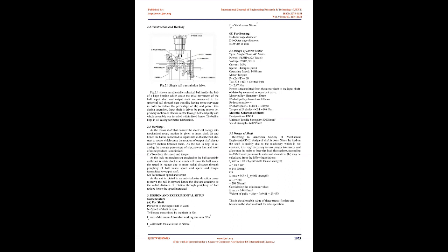2. Principle of operation. 2.1 Single ball transmission drive. Single ball transmission drive works on the principle of continuously variable transmission, CVT. In such transmission, a device or mechanism is designed in such a way that speed reduction or acceleration of speed is achieved continuously with respect to time, operation, or process. Fig. 2.1 shows an adjustable spherical ball inside the hub of a huge bearing which causes the axial movement of the ball. Input shaft and output shaft are connected to the spherical ball through cast iron discs having some curvature in order to reduce the percentage of slip and power loss during operation.